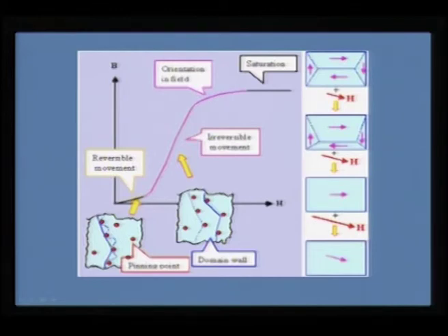As a result, a boundary is created here, and this wall is reluctant to move, but once you start increasing the magnetic field strength, you can see that this wall has moved here, and as a result a bigger domain has developed. Once this pinning is overcome, then as you increase the field, you can see that a bigger domain can emerge out of the field. So, once a domain picture evolves, you can keep rotating the domain according to the field direction, and that is what you would see here.